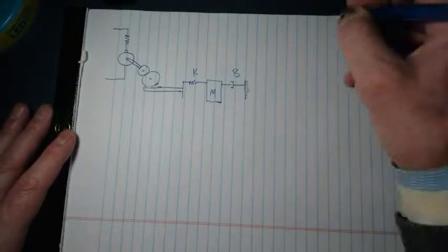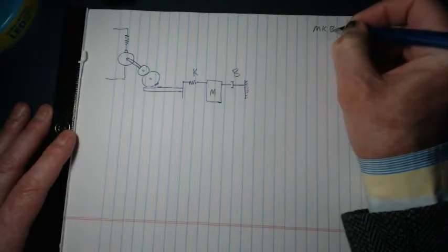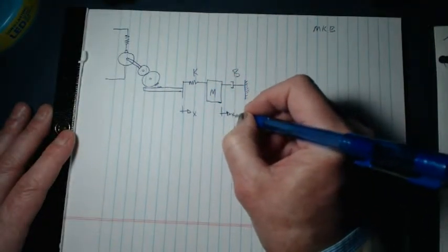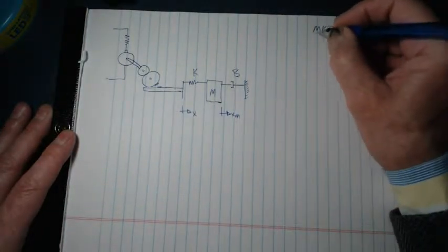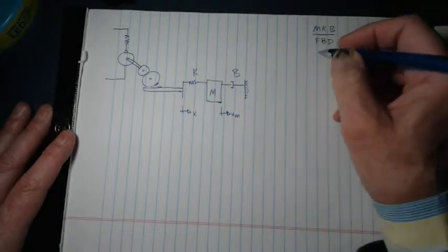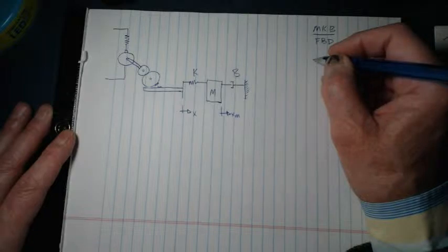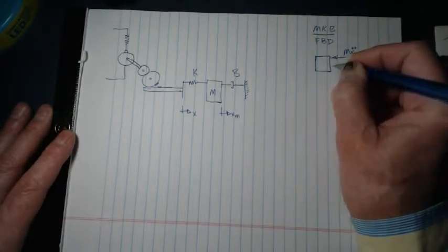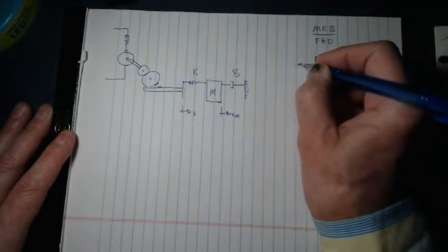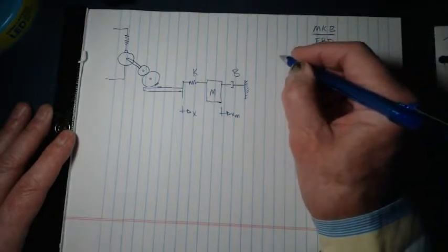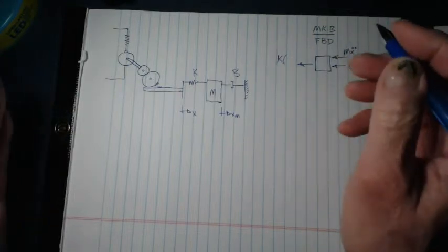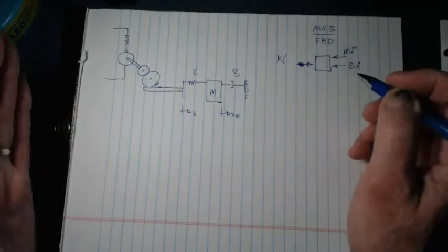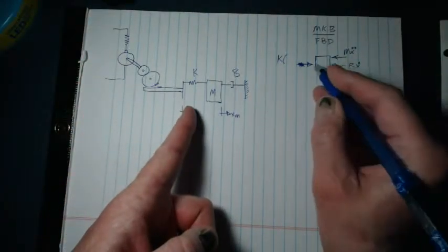Now, before we start, I'd like to talk about the mass spring damper system. For this system, there's an x, and then there's going to be x of m. We've already done a free body diagram for this when we did our spring system. We're going to look at m x double dot, and b x dot. And on this side we've got a k, and this force, let me put it in the other direction, because if I move this in a positive direction, this force gets bigger.